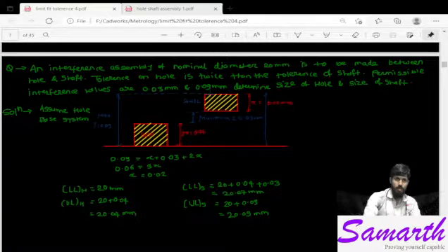Once we have got the values, the lower limit of hole will be 20 mm itself, that is the nominal diameter baseline. Upper limit will be the lower limit of hole plus the tolerance on hole, that is 0.04 mm. So the upper limit is 20.04 mm.